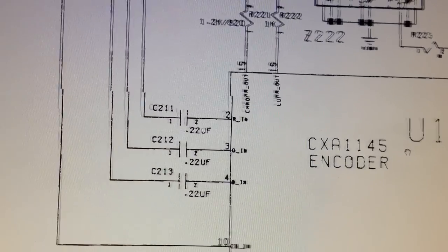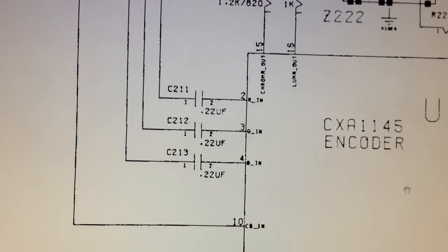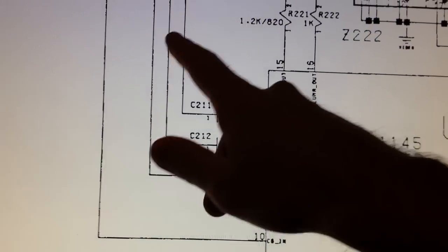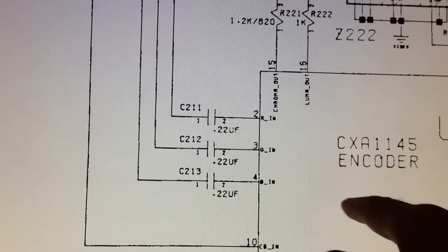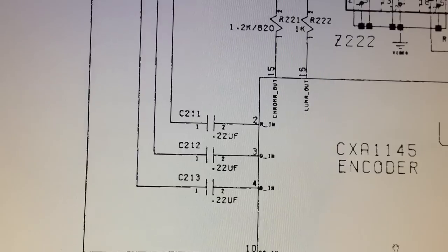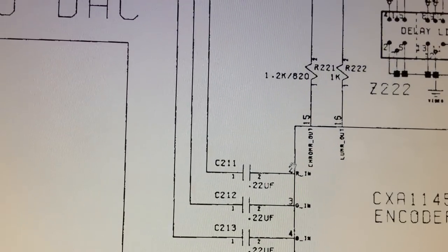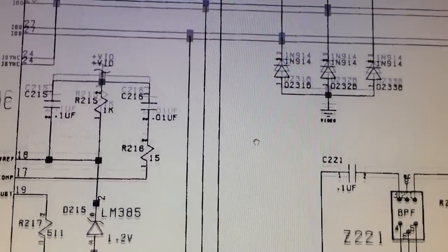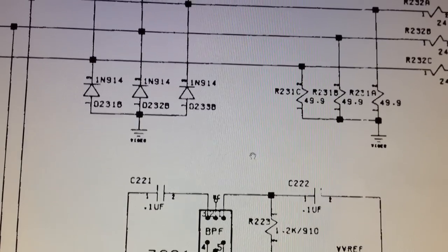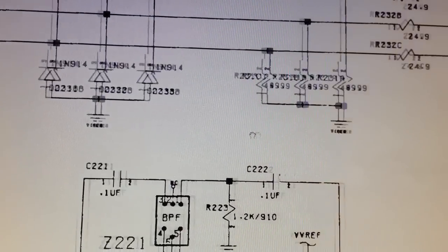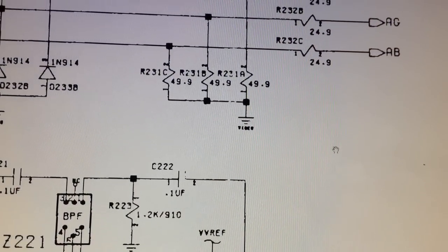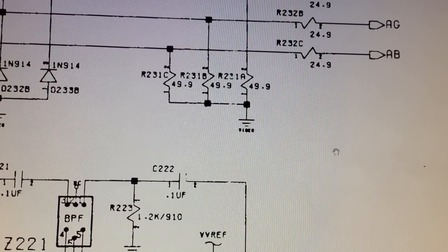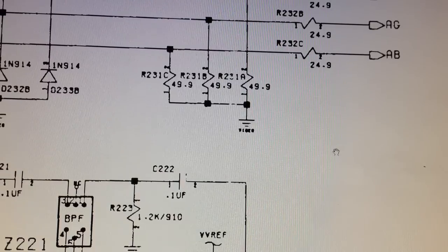So I don't think that there's anything wrong with the RGB signals, because we did get a picture from the composite video output, so that means that there must be something coming into the inputs of the video encoder, or the video encoder wouldn't have anything to encode and there would be no picture on the composite video output. So I think that the reason I'm not getting any picture on the 23-pin video connector is that there is some problem with the composite sync signal, or a problem with the switching voltage.